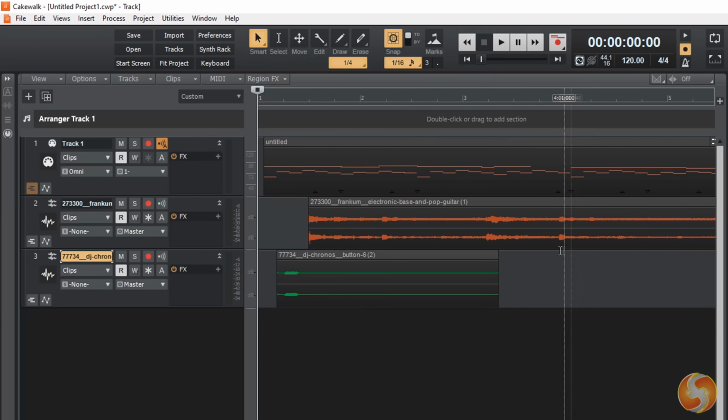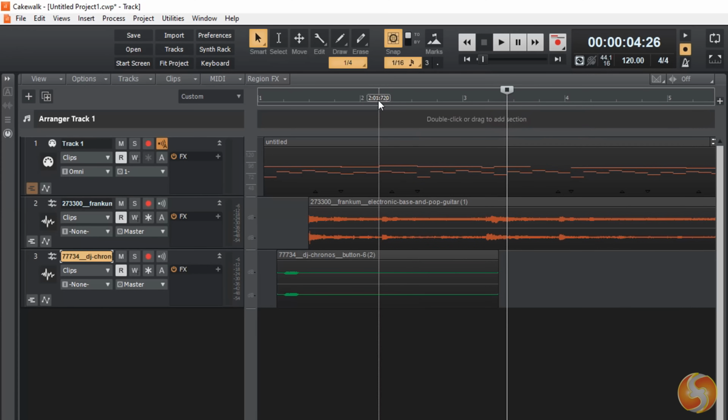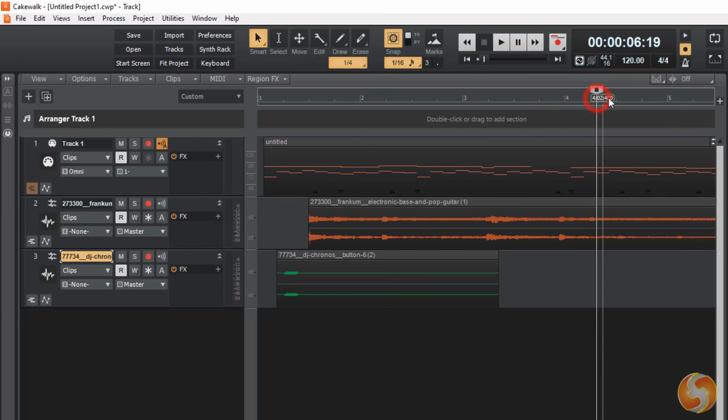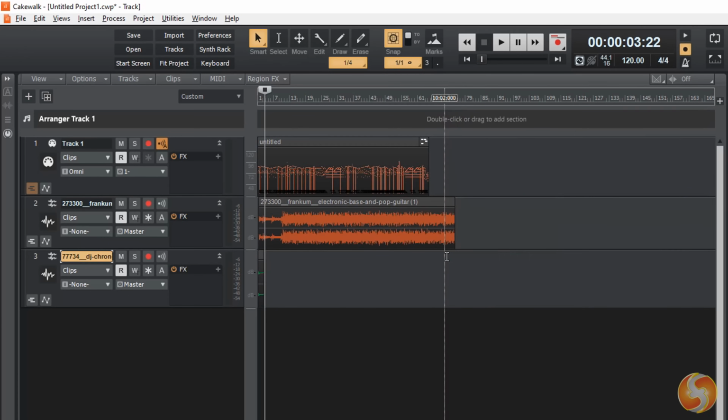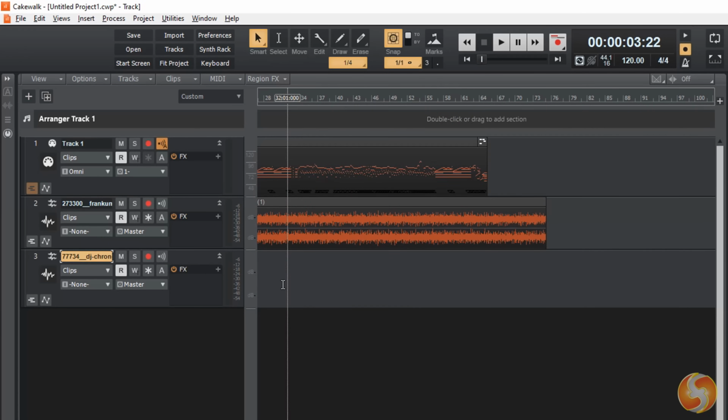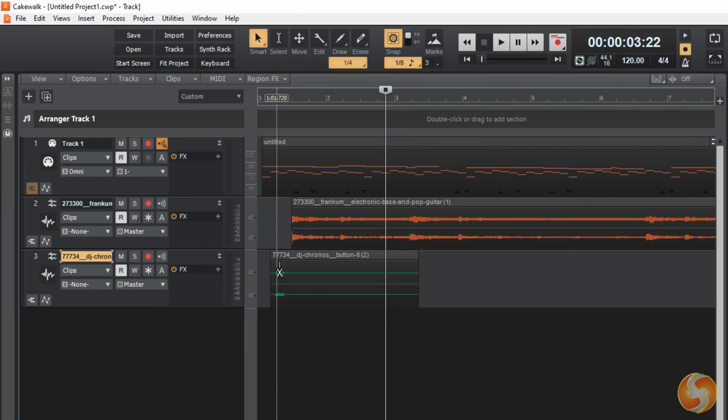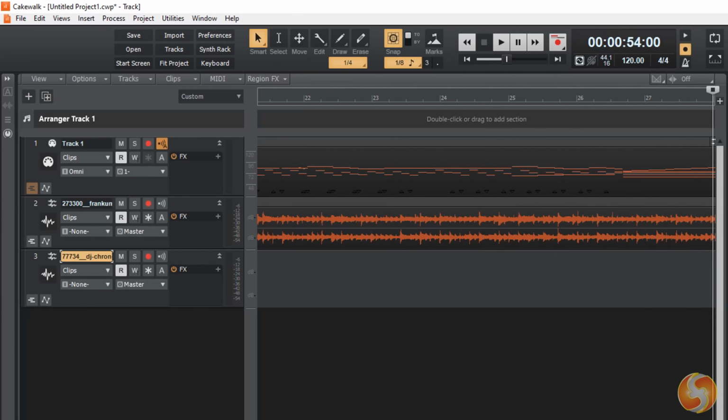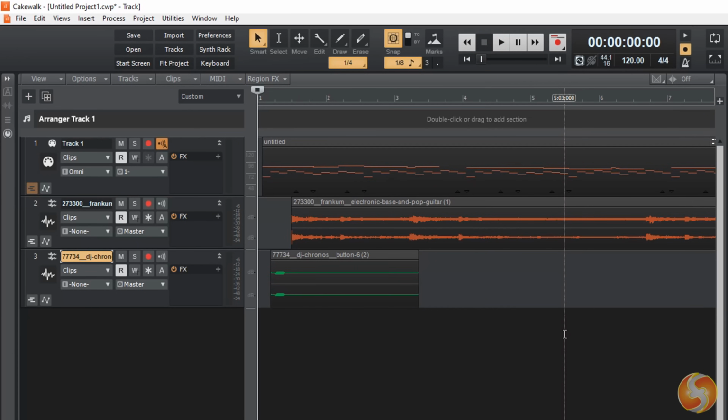The timeline content is measured in bars and beats on top, with the current time placement represented by the main marker and by the timer on top in seconds. You can zoom in and out by holding down the Alt key and using your mouse wheel. You can also move fast through time with the sidebar on top. Use the spacebar key or the play button on top to play back and stop.